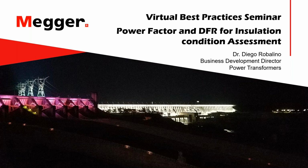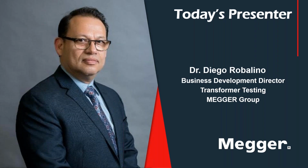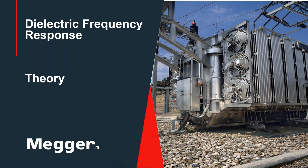Okay, with that being said, let me introduce a little bit of the topic right now. We're going to talk about dielectric frequency response. What we were talking about originally in the initial presentation was power factor and narrow band dielectric frequency response, and I want to be clear about the difference. Narrow band is part of the power factor test set, and that is a test that you run between 1 hertz and 500 hertz.